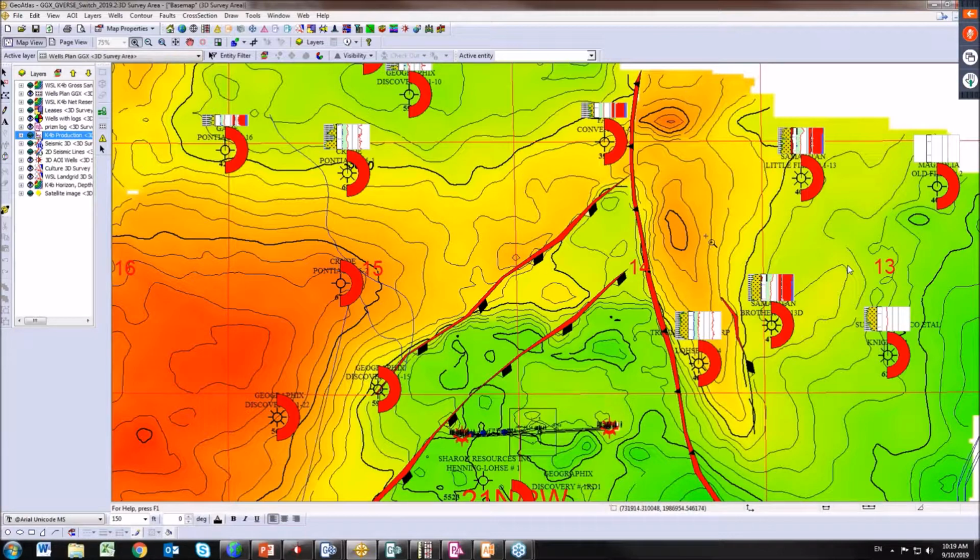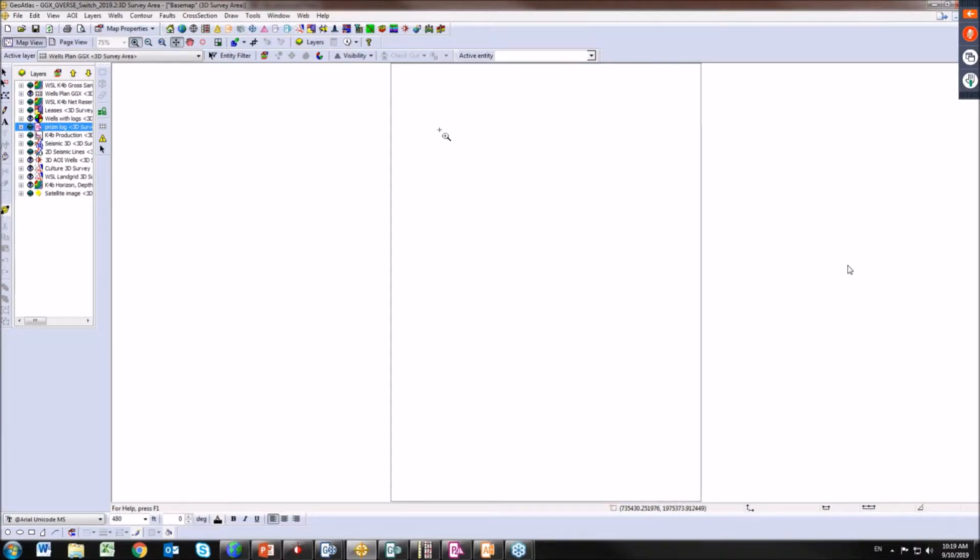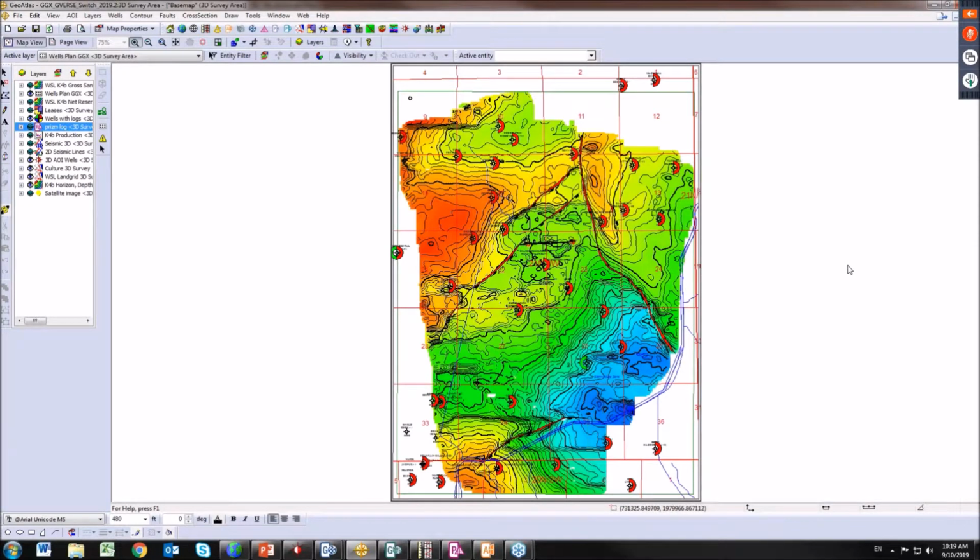And if you want to do some mapping to see the porosity, or if you want to see permeability, I can also display this information to give me guidance on the tendencies on my map. You can also display data that you created. You import horizons, use seismic interpretation, create your horizons map, time-to-depth conversion, whatever velocity or whatever map that you create in the seismic, you can bring it inside right here.